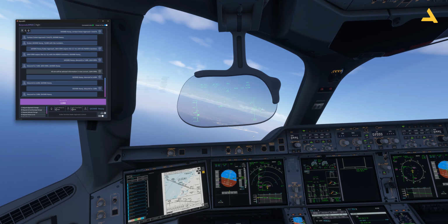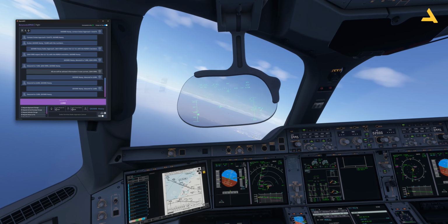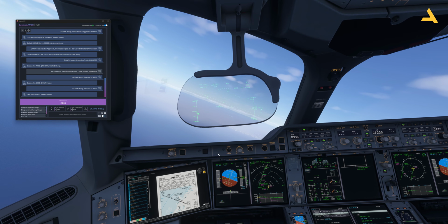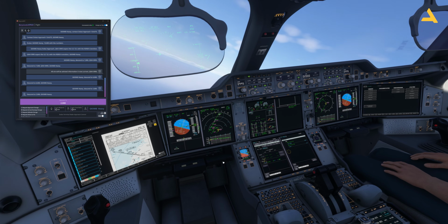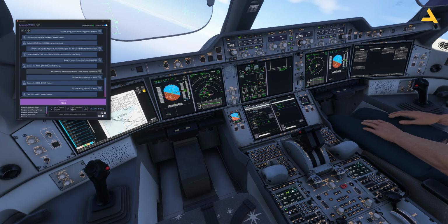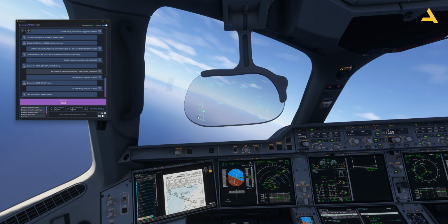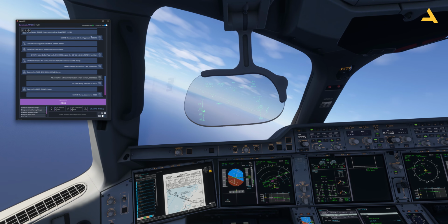So now you know if you are flying a plane and you want to get the weather information, you can always tune into the ATIS, and this frequency is always given over here. You can even, instead of using VHF1, use VHF2 for the ATIS and then VHF1 for the normal communication. But for this video, I just use VHF1 just to let you know how you revert back to this frequency.